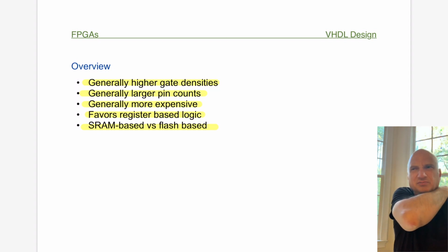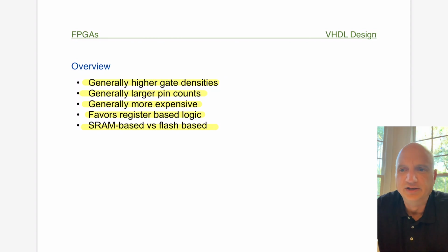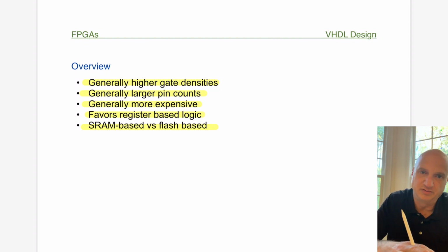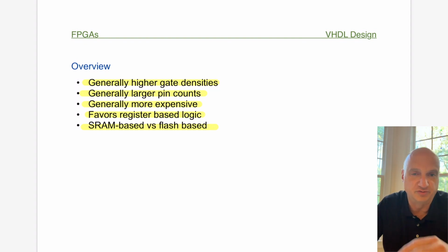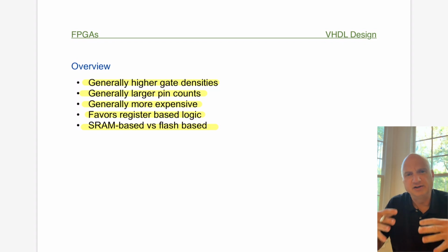But they also have some downfalls. Because they're made of flash, their densities are not as good typically. And so there are some performance hits there. So it's kind of a cross between a more dense CPLD with the non-volatile storage if you go with those types of devices. So what you choose really depends upon what your application is, what your price point is, et cetera, and your density of the design. So that's kind of, in a nutshell, the big picture.